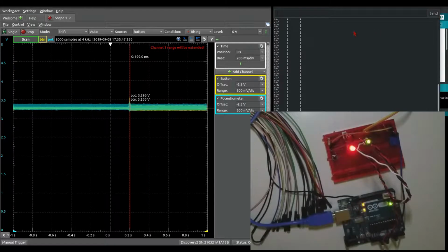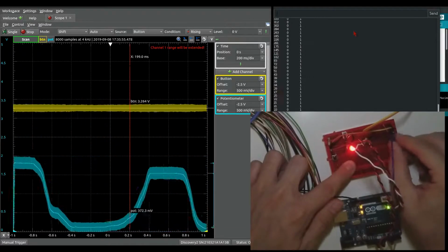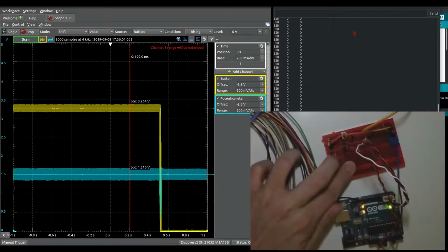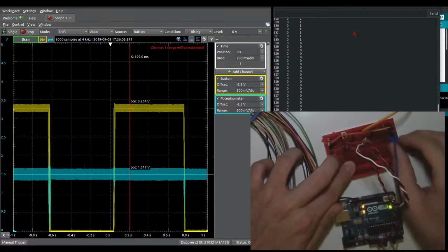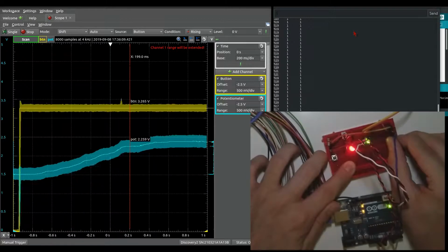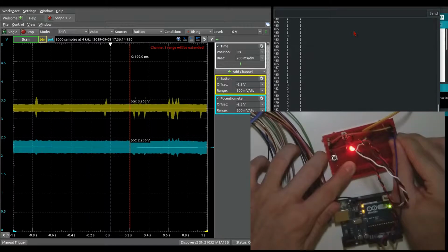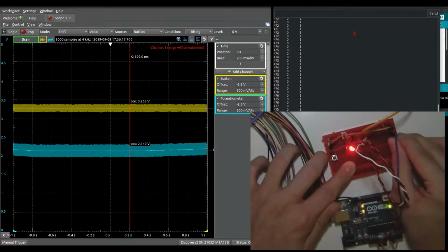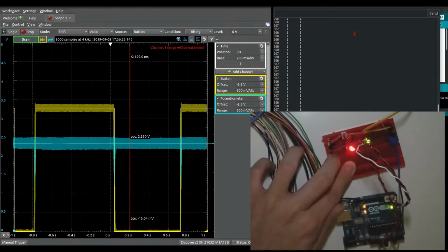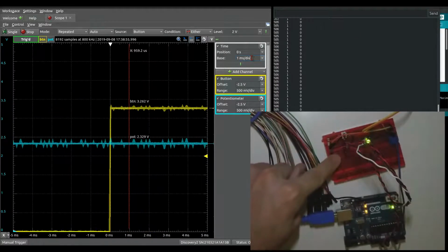The number on the left corresponds to a raw ADC value. The middle number is the state of the potentiometer, and the rightmost value is the state of the button. You can see that the state of the potentiometer only changes after it's above a very specific voltage. Here it's around 2.2. You can also see that the button creates sharp transitions from the high voltage to the low voltage. This is what creates a digital high and a low, or binary 1 and 0.